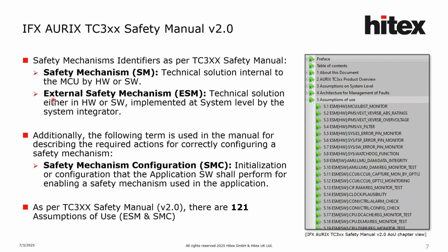The second is the external safety mechanism, short ESM: a technical solution, either in hardware or in software, implemented at system level by the system integrator. And as a last one, safety mechanism configuration, short SMC: the initialization or configuration that the application software shall perform for enabling a safety mechanism used in the application.